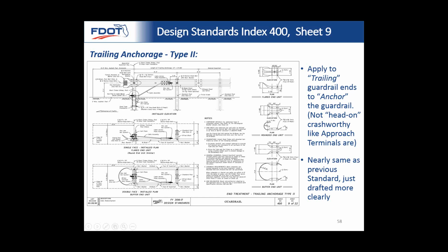Essentially, the function of this is to tie the guardrail down, to develop that ribbon strength so that if a vehicle hits it, almost all the way to the very end, you have redirective capability. If you didn't tie it down, then all these things would just pull away and it really wouldn't redirect you or anything. The vehicle would pass right through it. And so you always have to have some type of end treatment. So don't expect it to be hit from head on.